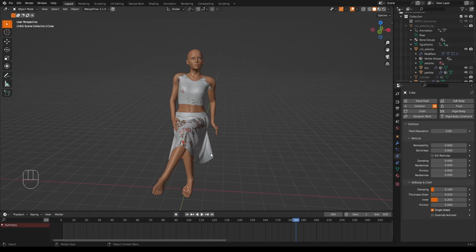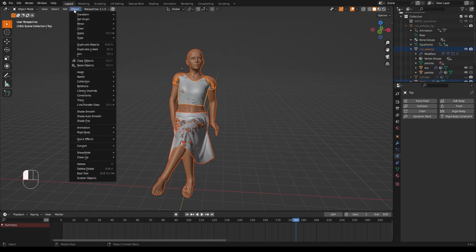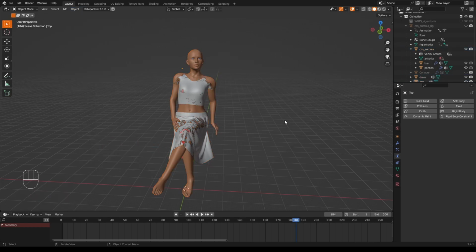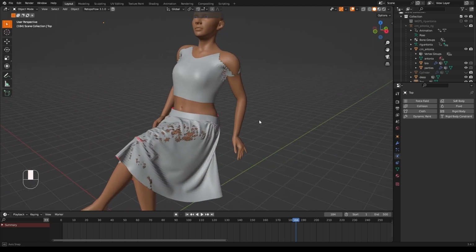Quicker too. Select the model and shift select all the other clothing and articles and anything else that you want to get involved in this, and go up into object and go down to convert mesh. That's a little bit counterintuitive, but now everything is applied and nothing's broken.